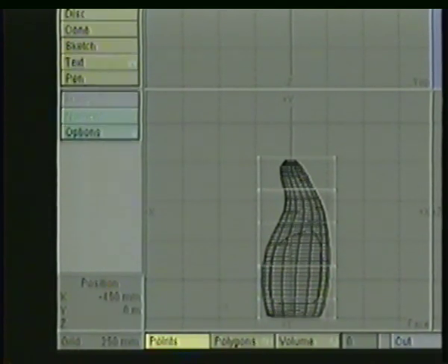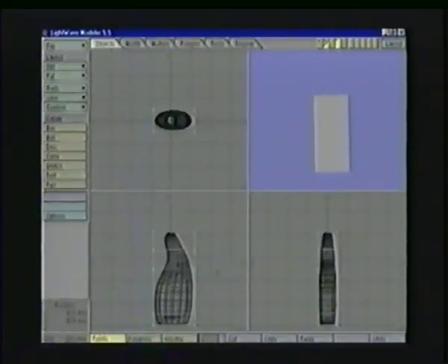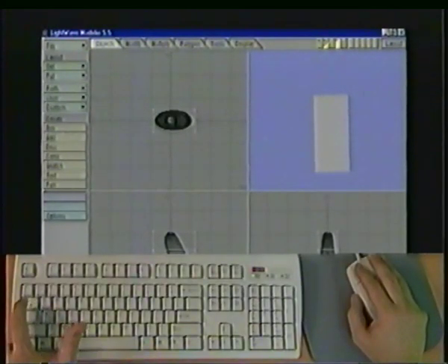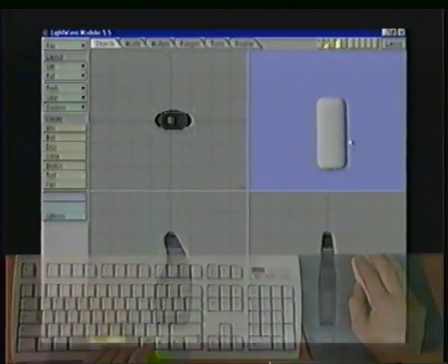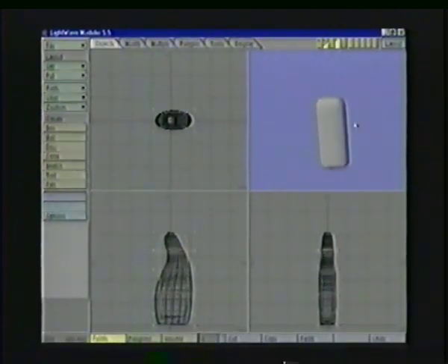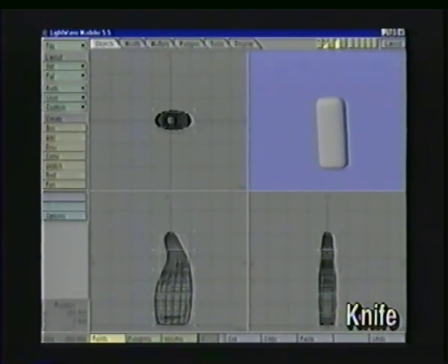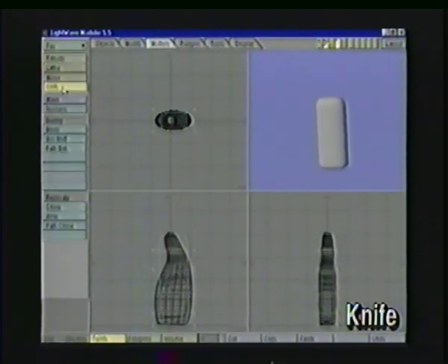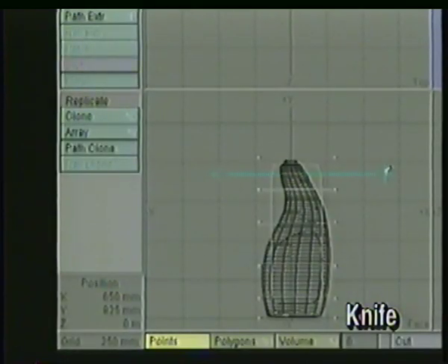I can do this either in polygon mode or in metanurbs mode. I'll go ahead and turn on metanurbs by hitting the Tab key, and that activates metanurbs. At any point, I can go back and forth between metanurbs or polygons. I'm going to go to the Multiply panel and use the knife tool to slice across, and I'll hit Enter when I'm ready to slice. I could drag with my right mouse and let go, and it'll immediately slice.